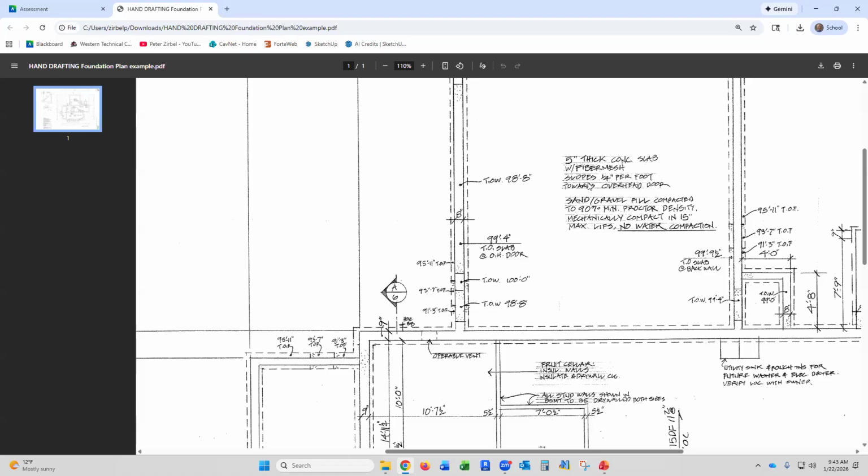Now, if you ever live in a house where they didn't slope the garage to the overhead door, which I did at one point up in Wausau, you're going to find out that all your snow and salt that melts off of your car into your garage ends up running to some interior wall instead of out the overhead door, and then it sucks up the drywall and all your drywall falls off because it all got wet.